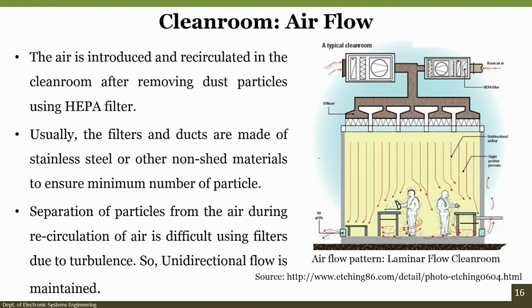Next one is about the airflow, and you can see in this particular schematic that the airflow, which is a laminar clean room flow, is very important. In this case the air is introduced and recirculated in the clean room after removing dust from the HEPA filters. You can see here the air comes from here, it passes through the HEPA filters, and usually the filters and ducts are made of stainless steel, to ensure a minimum number of particles.